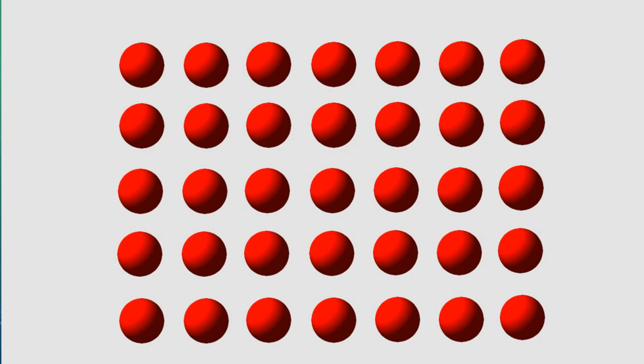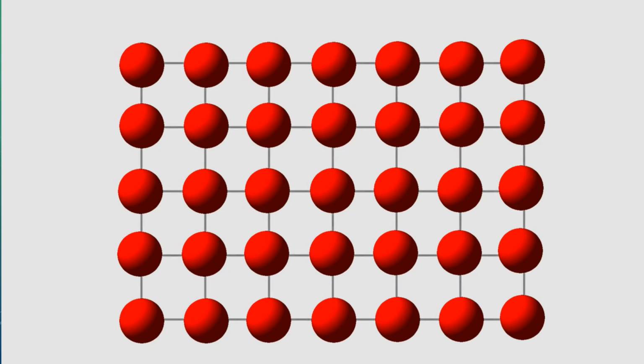Here's a simplified two-dimensional version of the atomic structure of nitinol, but one that captures the essence of why it has a temperature-dependent memory. The crystallites of the small grains have a nice, tidy, highly symmetric arrangement. The atoms sit on the corners of squares. At temperatures above 500 degrees Celsius or so, the nitinol will be shaped into whatever form is useful. For example, the spring I showed you earlier.